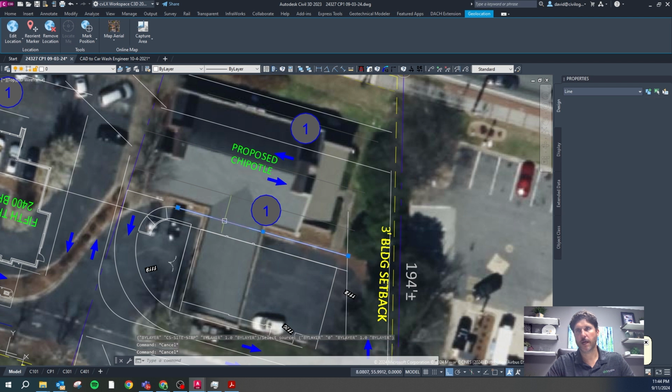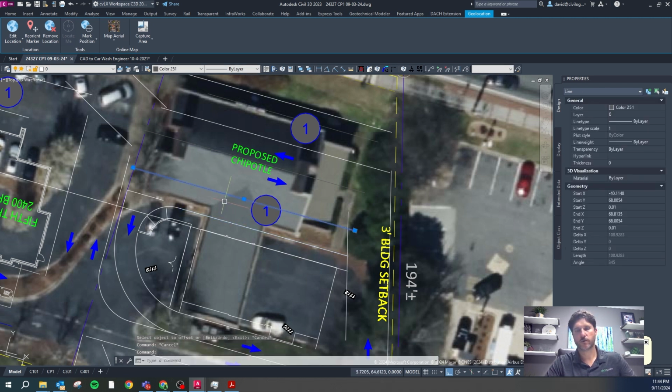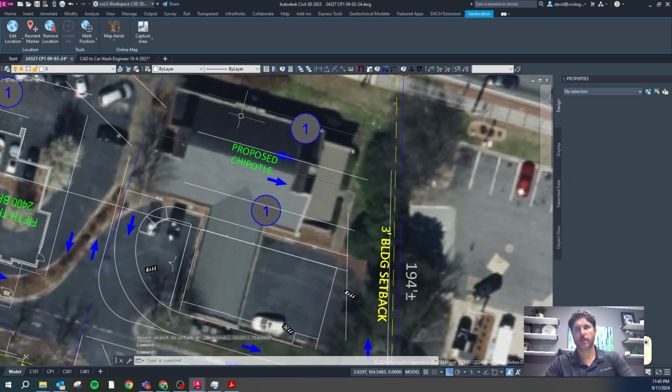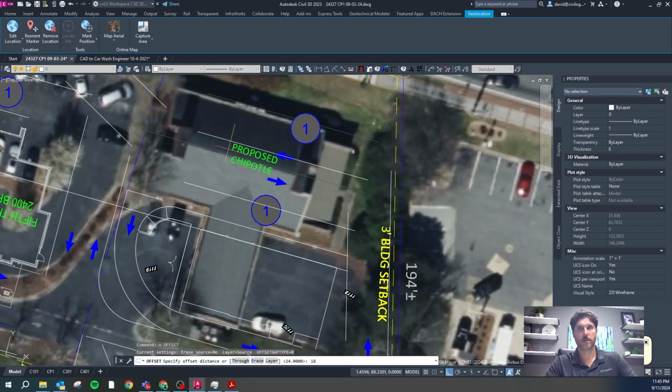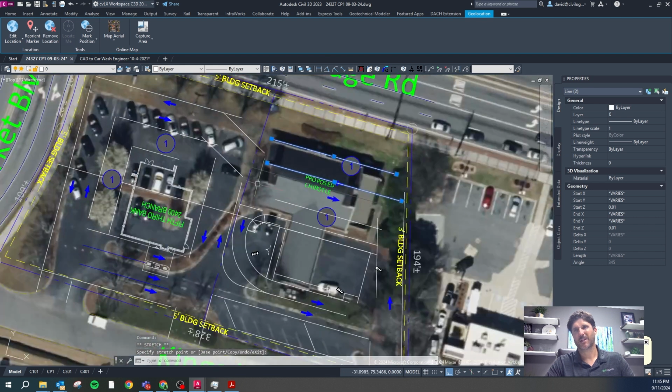So if I go back to, maybe I just put a 12-foot drive aisle, which is already there, and then a 24-foot drive aisle, and then an 18-foot parking space, 18 feet. And so now I can fit some more parking in, which I really like. My transition's a little bit worse, but it's not that big of a deal.